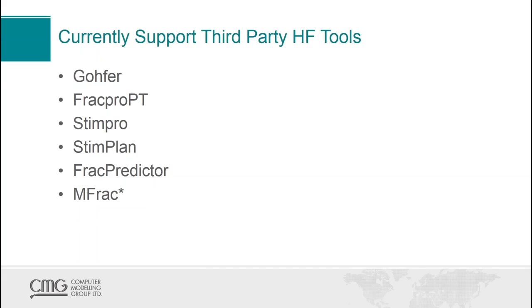So one thing we like to do is allow the history matching process to back into what matrix permeability, capillary pressure, and rel perm curves should look like by using Corey functions and allowing ranges of values for all of the endpoints and the exponents to help us sort of home in on what the correct values should be. And of course, the longer your production history, the more likely that you might have multi-phase flow in the reservoir rock itself. And so you're going to learn more over time what those correct values should be.